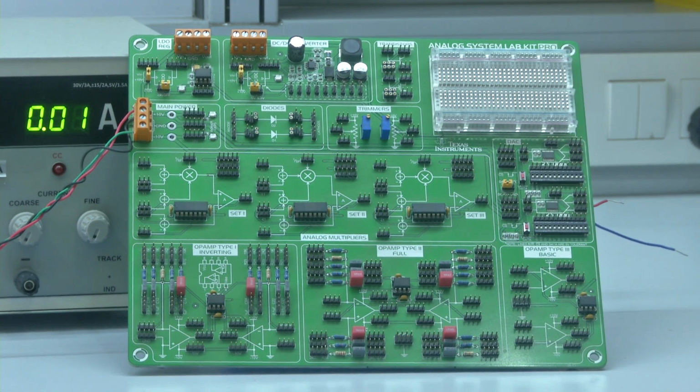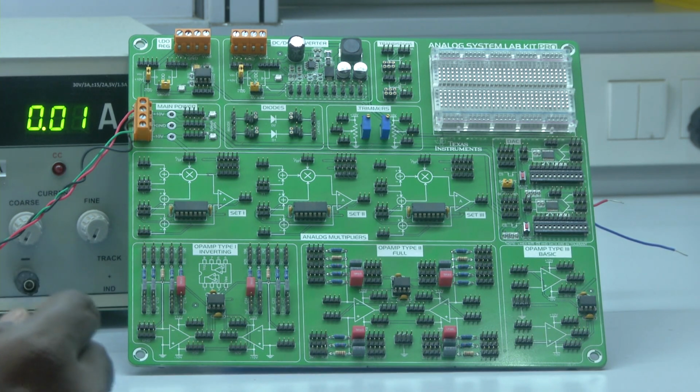Okay. Now let us see the connections for implementing both the inverting amplifier configuration and the non-inverting one. Let me start with the inverting amplifier configuration. In order to provide a gain of 10, if you recall the circuit that we have used, we require a feedback resistance of 10 times the input resistance. So, I will take an input resistance of 1 kilo, so that the feedback resistance is 10 kilo. Right. Let me take a few jumpers in order to do the connections.